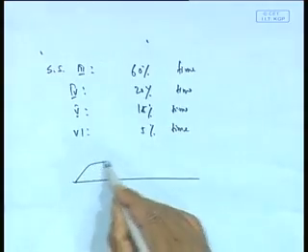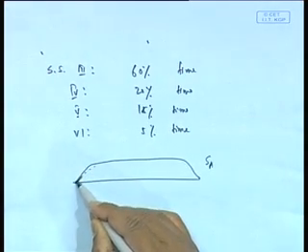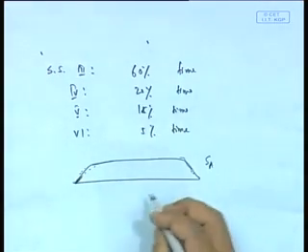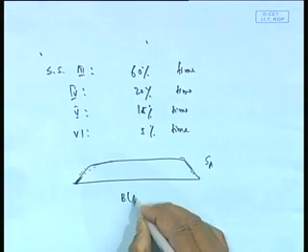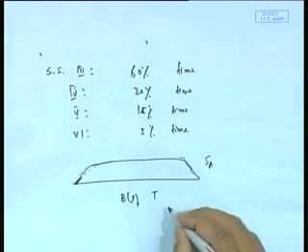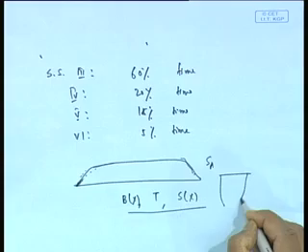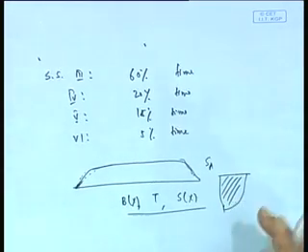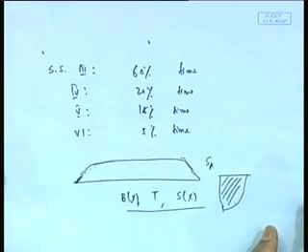All I require is, when you are doing a lines plan, if you recall, you end up actually making a section area graph, SA graph, and you end up getting another one, what you call the water plane area graph, right. Essentially you will be knowing each section in a design: local breadth B, local draft, and section area. These 3 parameters, normally you are drawing a section shape. In fact, with these 3 parameters only, one can estimate using Lewis form and other forms, added mass and damping.